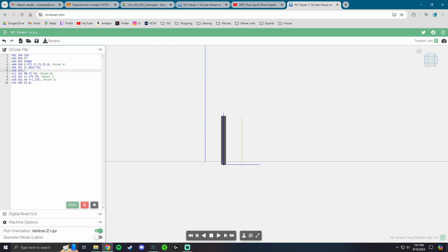Because once I switch the absolute relative coordinate system, G91, whatever I subtract, if I go down -2, it doesn't know where 0, 0 is anymore. We always have to tell it where it is or make sure that we include what we took away. So if we took away 2 inches and we only add 1, then you go -2, you add 1, you're only at -1. You don't really go back +3. In absolute, that would work. But in relative, you always have to make sure what you take away, you put back and then add more.